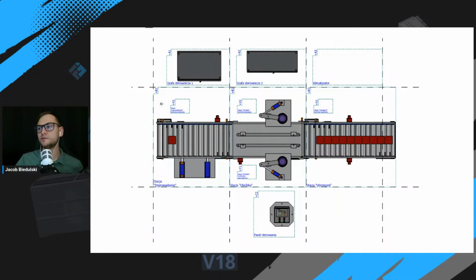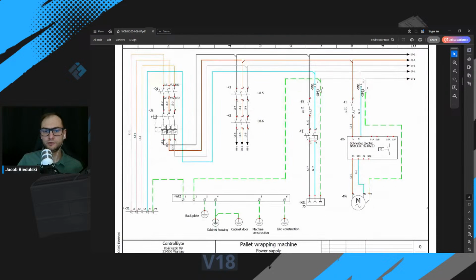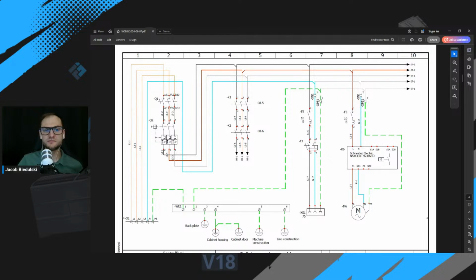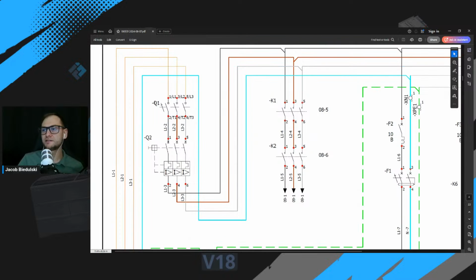And in almost every electrical diagram with the complete sheet, you will find a page with the full layout of the machine and a description of the locations and functions, okay? If you go to the first page with the schematics, you will find the designations of the devices. This is, for example, a disconnecting device. It is designated as Q1.